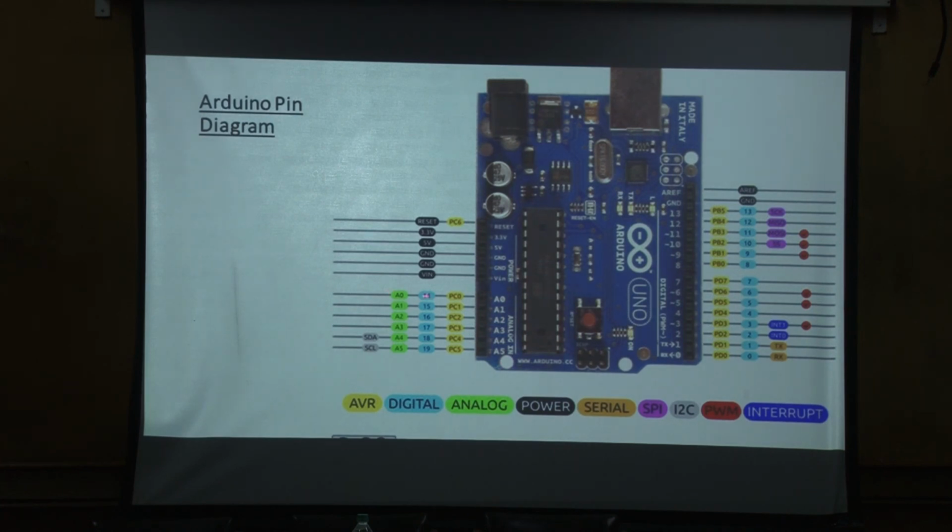So if I connect a wire here, a sensor here, onto A0, then basically I am connecting the wire from the sensor onto the A0 pin number, and it understands that whatever is coming in from there is coming as an analog input. So I can convert that into digital using an ADC and then record it and keep it, or do something with it.